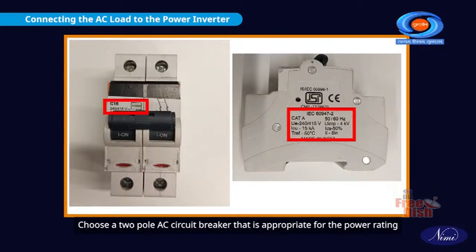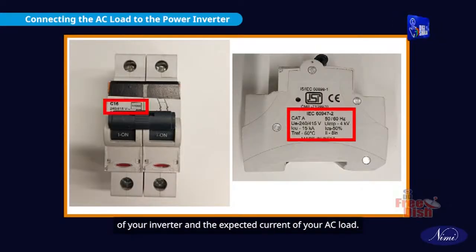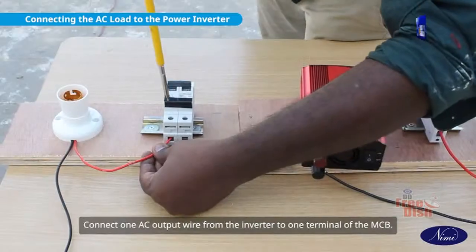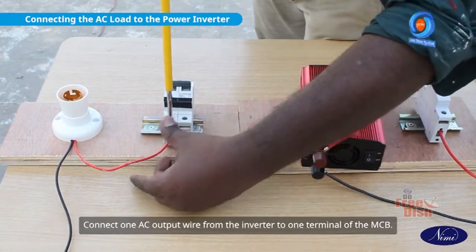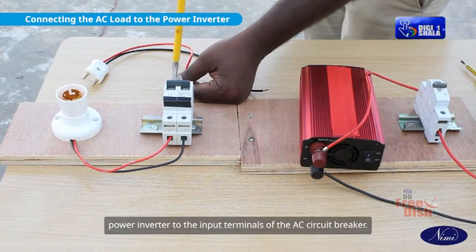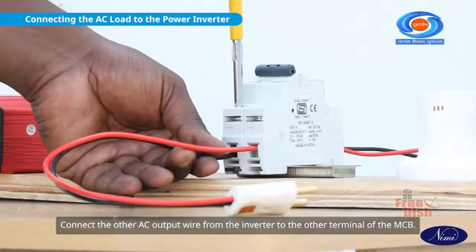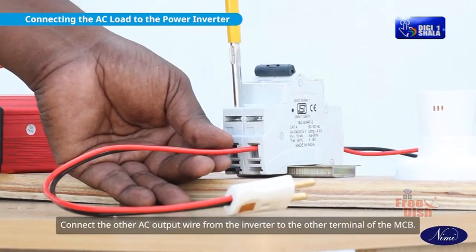Choose a 2-pole AC circuit breaker that is appropriate for the power rating of your inverter and the expected current of your AC load. Using appropriate size of wires, connect one AC output wire from the inverter to one terminal of the MCB. Connect the AC output terminals of the power inverter to the input terminals of the AC circuit breaker. Connect the other AC output wire from the inverter to the other terminal of the MCB.